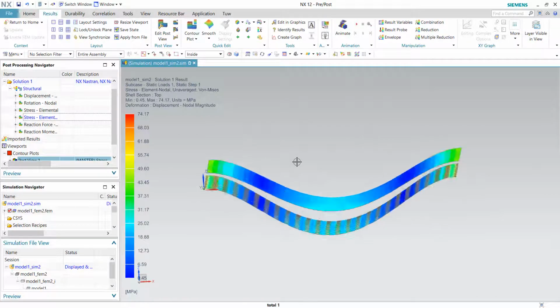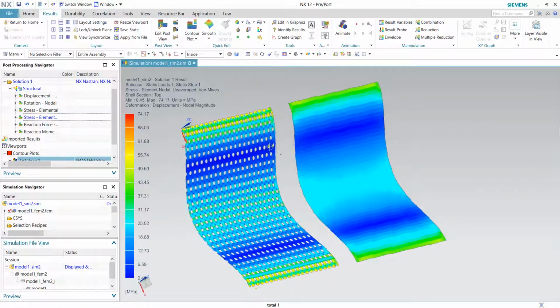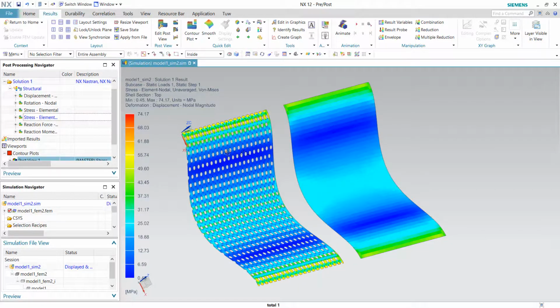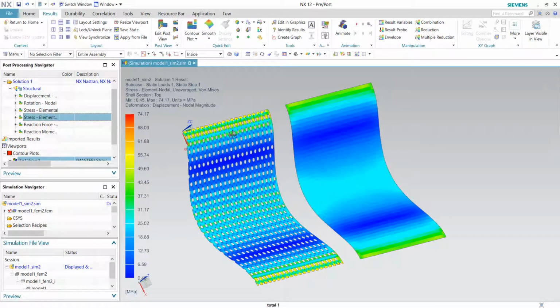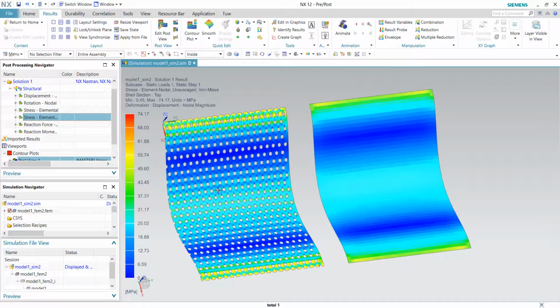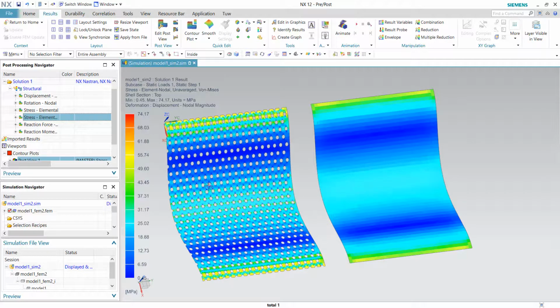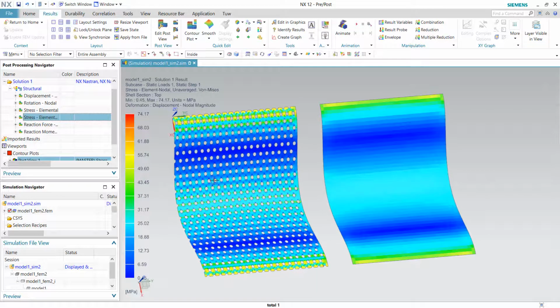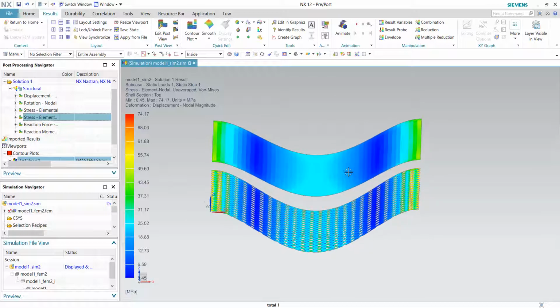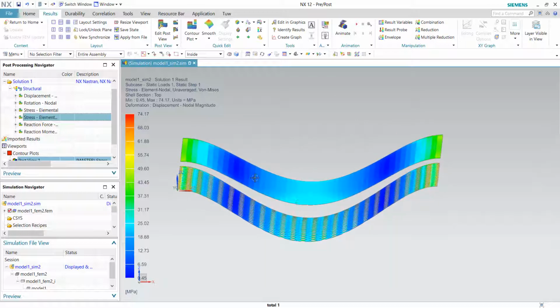So we can't do much on the stress result, because stress result for linear static is actually geometry dependent. I repeat myself again, stress result for linear static is geometry dependent. There is no way we can get the equivalent stress result between the two, because the geometry is different, full stop. Unless, but if you look into the general contour plot in a general manner, we can still see that